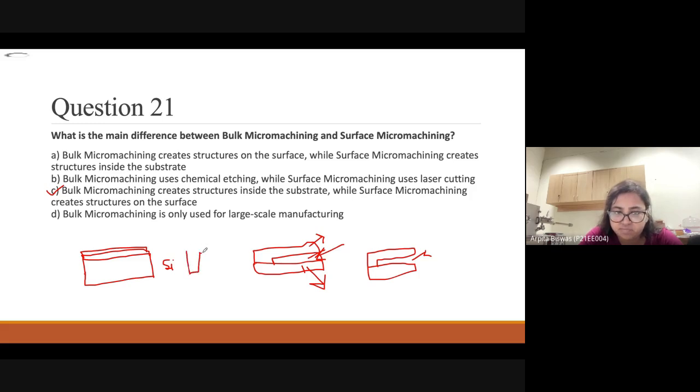The diaphragm type is a pressure sensor. It is given some force or pressure, so there is a change in the diaphragm, which changes a property of the sensor, like the resistance or some other electrical property. So the input is the pressure or force, and the output is a change in an electrical property. This type of structure is present here.